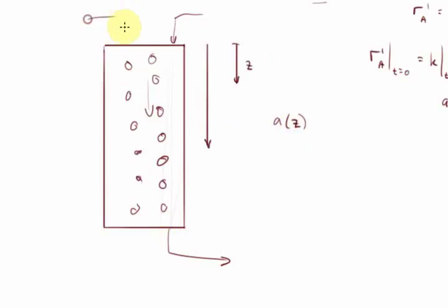We are losing activity down this tube. At the same time, we've got our primary reaction going on. So we are feeding our reactant in, Ca in here, and it's reacting. So fine, we are losing activity, but we still have some activity wherever we look. And so we are converting A to the product as that's falling. So both those things are happening simultaneously. So we need to be able to predict this exit concentration Ca, given that the activity we are seeing up here is not the same as the activity down there.